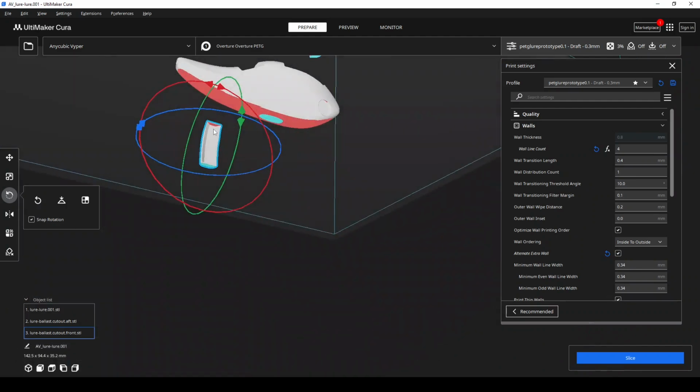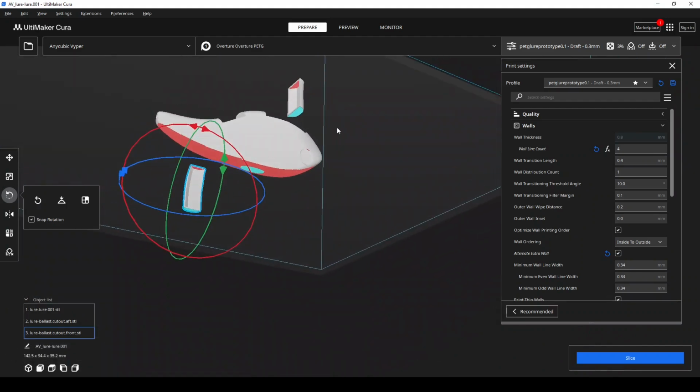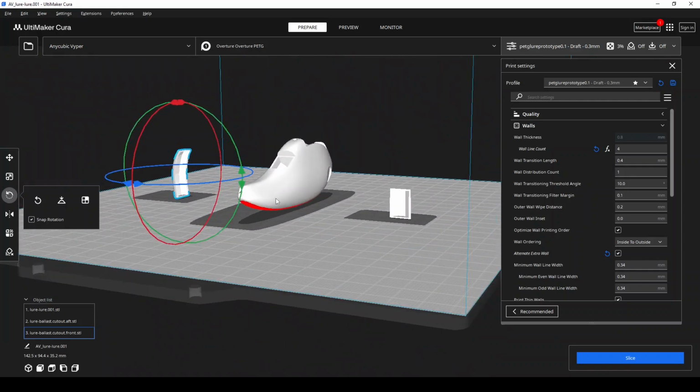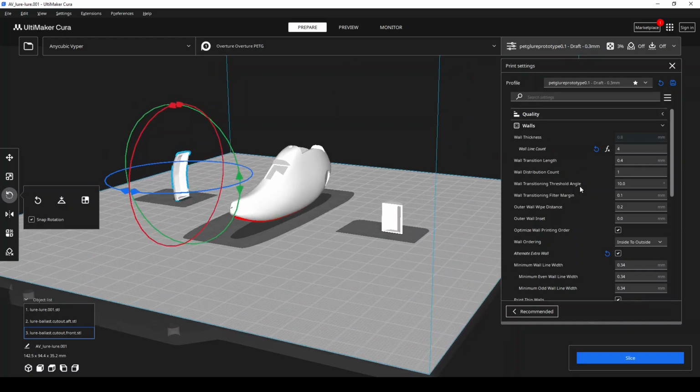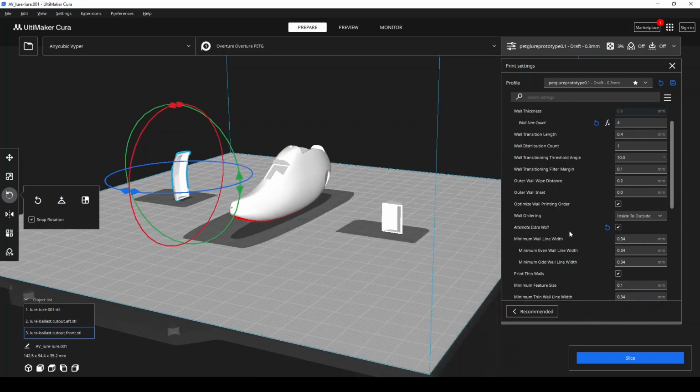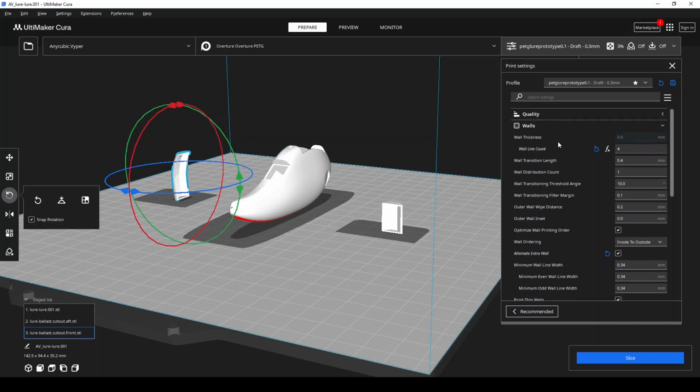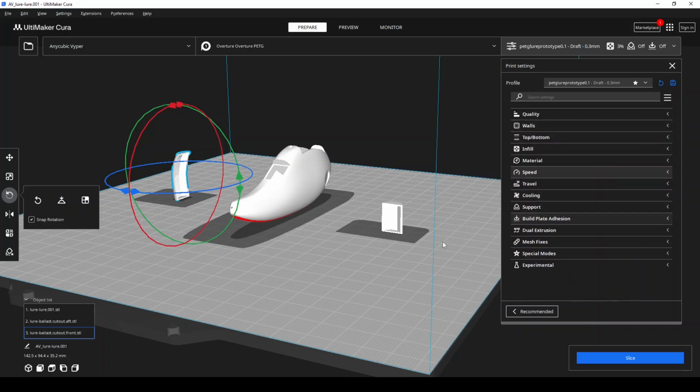Those will need supports here. You could design those pieces so that that's at an angle, but I really want to just make this simple. For now, while we're running the slice, make sure that you don't have any supports on, and make sure that you don't have a brim or a raft or any other type of, what do they call it, build plate adhesion. Because we're trying to determine what is going to be the weight in grams of just the filament. And later on, when we're done, we will add the supports and we will add the brim.